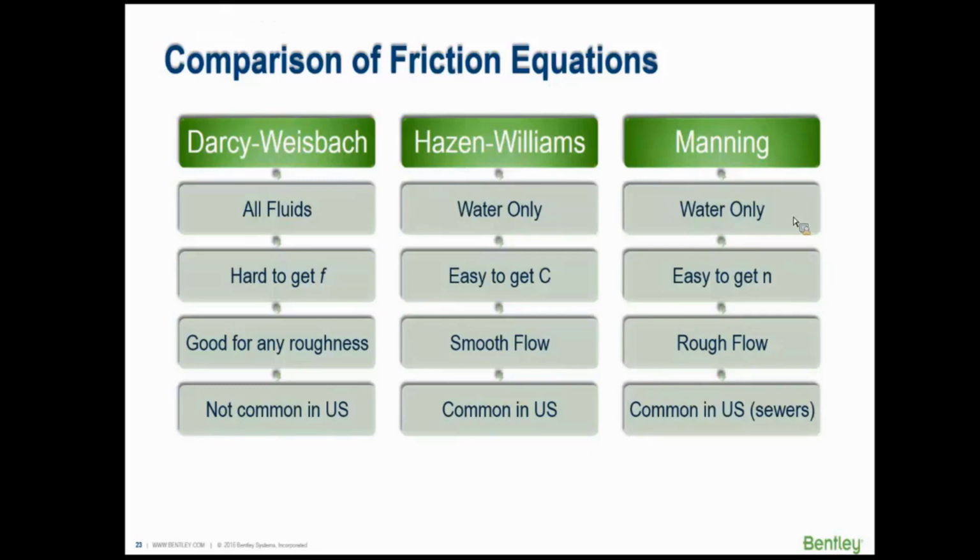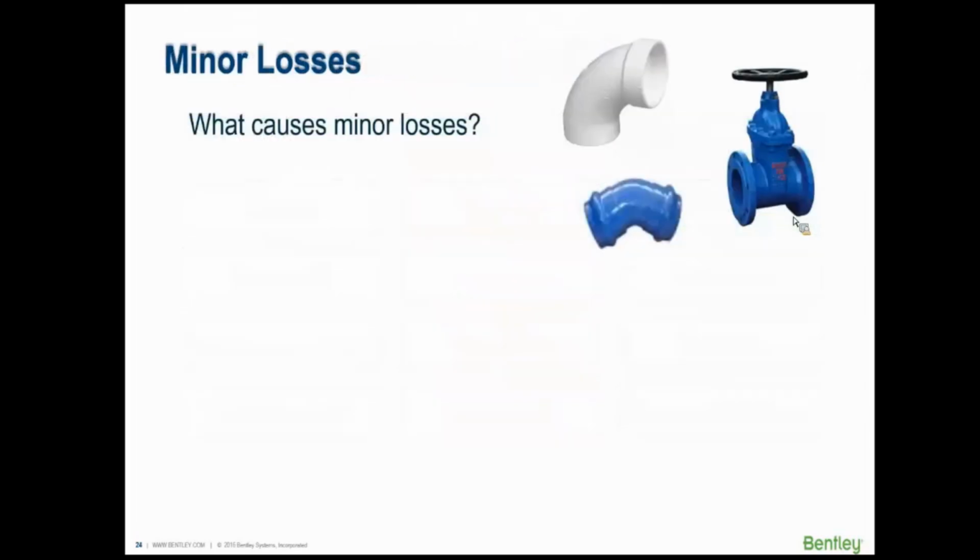Okay, seeing all that, we now know everything there is to know about calculating head loss. And the answer is no. There are things called minor losses. Now, what are minor losses? Anybody who says their losses are less than 21 years old are wrong. They're losses caused by things like bends and fittings, joints, valves, things of that sort.